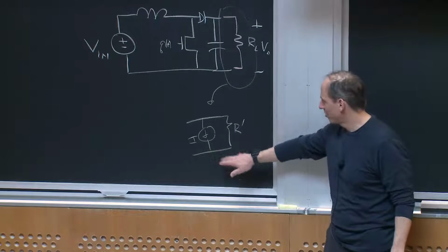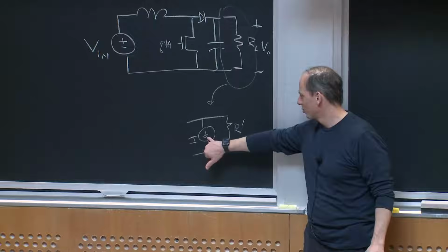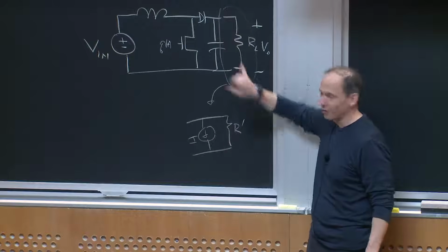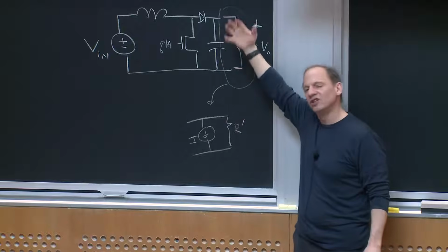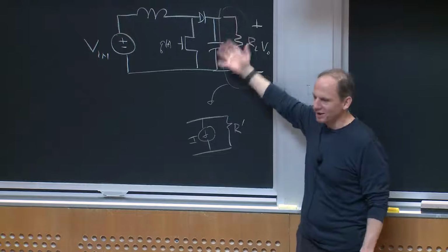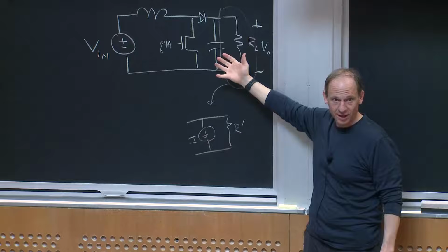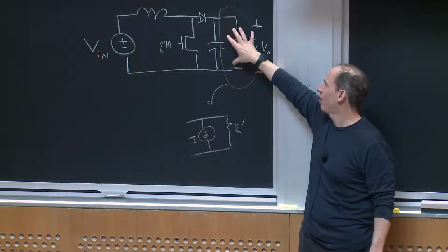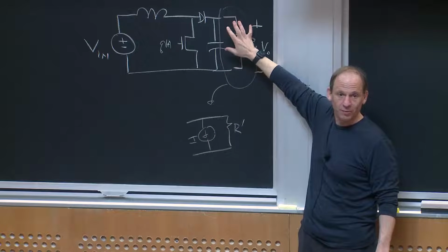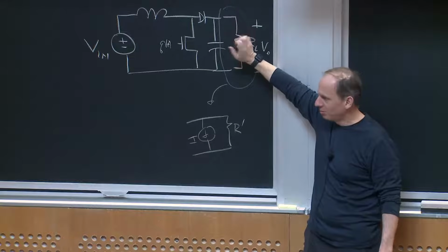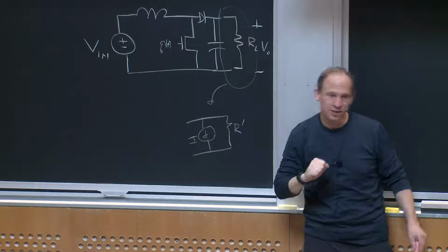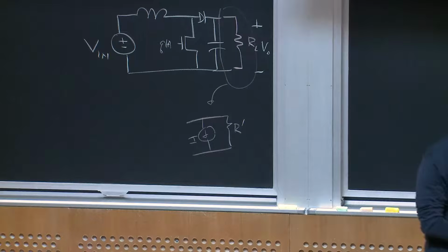And I'm just doing the simplified case where the Norton source is 0 and the resistance is RL, okay? But that's just a way of saying, in general, you would worry about exactly what the load looks like, not just in terms of how much current it draws, but exactly what the load looks like can affect the dynamics, okay? But for simplicity, let's just talk about resistive loads, which is a very common case, okay?